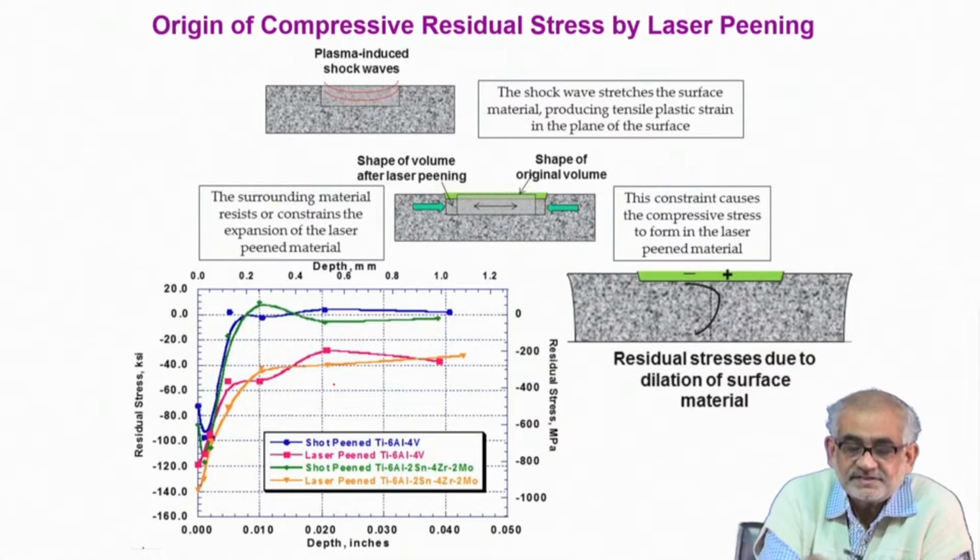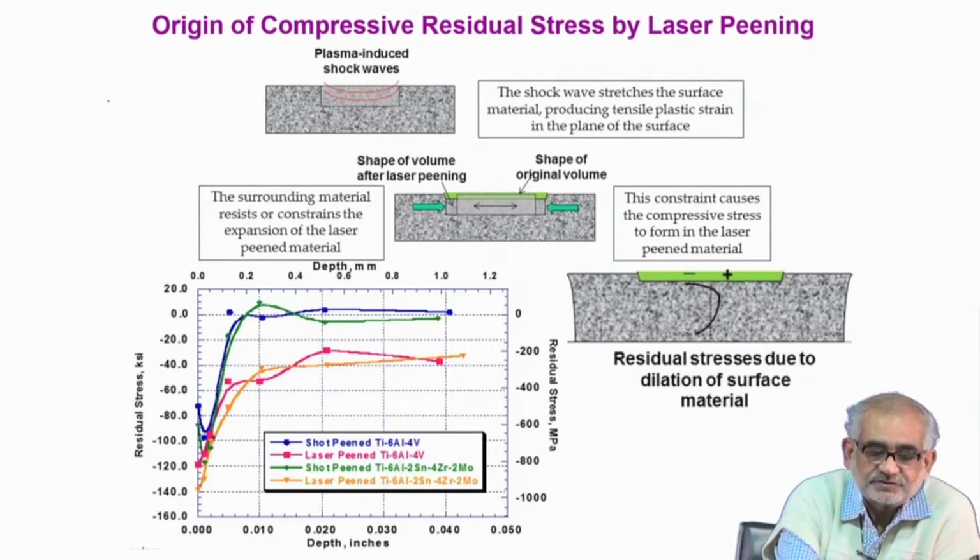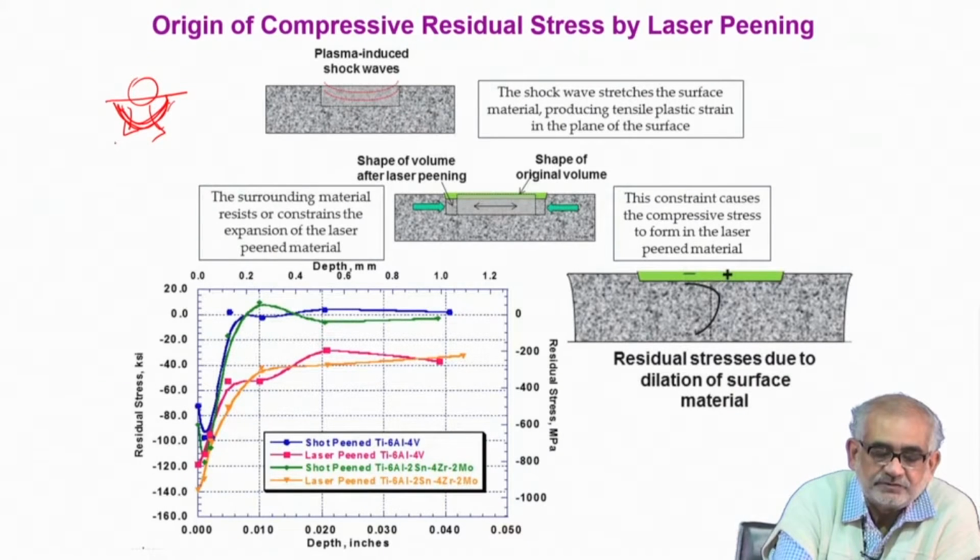So just like in shot peening, or even shock peening, when the striker hits, we saw that this would be the deformation zone below the object, the projectile, which is incident onto the surface. Initially this is how the material will tend to deform, but then subsequently the material wants to spring back, and that's how we create a state of compressive stress onto the surface.